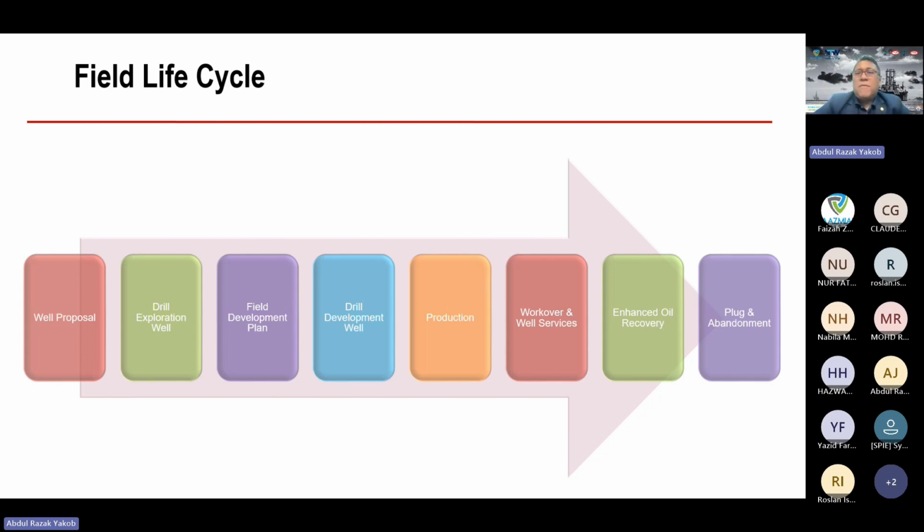Yeah. Conventional, for example, you have oil in a reservoir, yeah, just like what we saw just now, what constitutes an oil and gas formation, that is source rock, trap, and seal. So within that, you have 100% oil, and conventional development can only come out with a maximum of 38% of what the oil has inside here. 38 only, and then you have the secondary water flooding whatsoever that will increase to like 45, maximum 60.